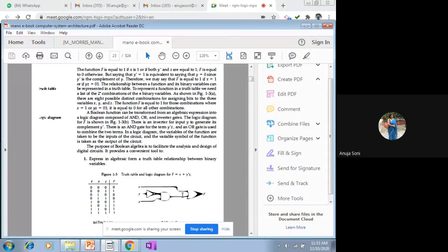So if the purpose can be served with the simplified version, why is there a need to unnecessarily increase the number of logic gates? If the number of logic gates is unnecessarily increased, it will unnecessarily increase maintenance cost as well as other kinds of cost. So that is the only significance of simplifying the Boolean expression, so that subsequently it reduces the number of gates required in drawing the logic circuit diagram.